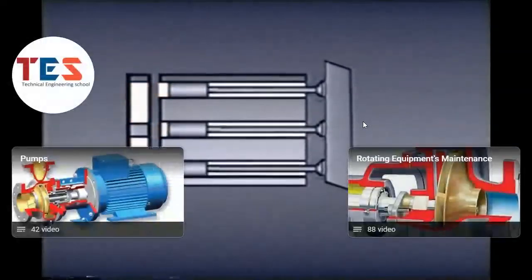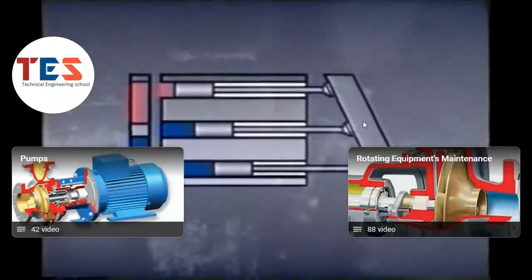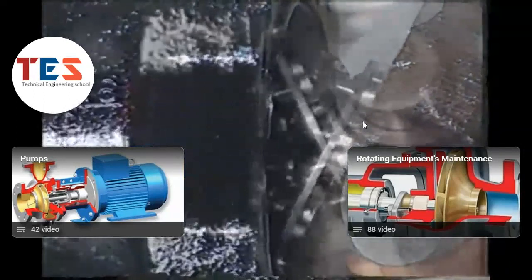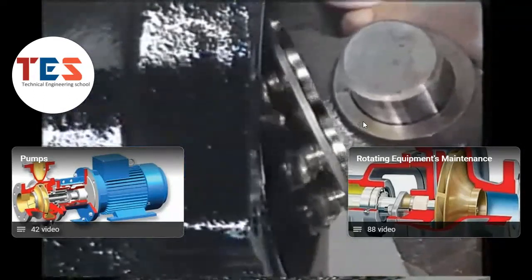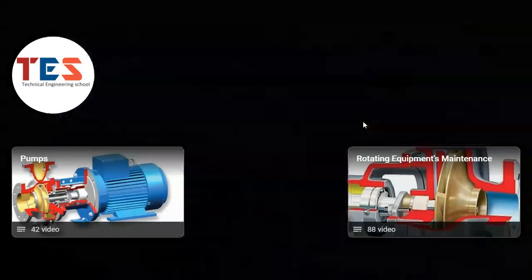Usually, to reverse direction, the motor is stopped. When the motor is restarted with the swash plate tilted over center, the piston shoes, which had been rotating in one direction, go back the other way, turning the cylinder barrel in the opposite direction and reversing the direction of the motor shaft.